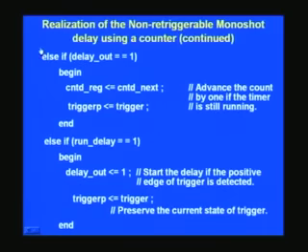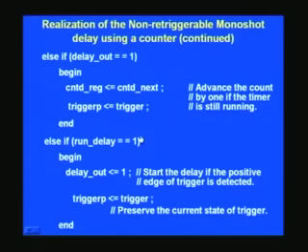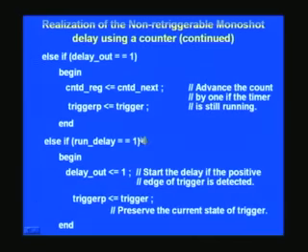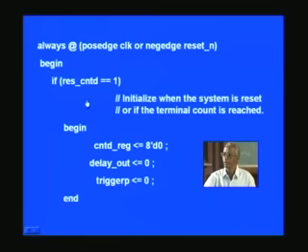We have said earlier that muxes are put cascading each other, and we will see one more point before we wind up today's lecture, and that is what this implies: it is a priority encoder as such. See, we have an if statement occurring very first. So if this condition is satisfied, it will process this and then quit the whole thing.